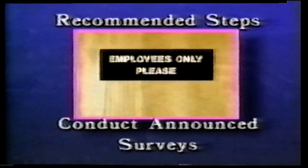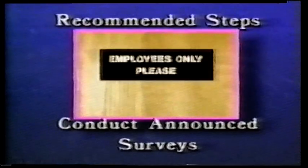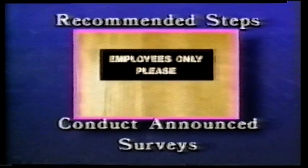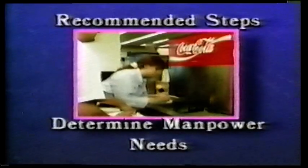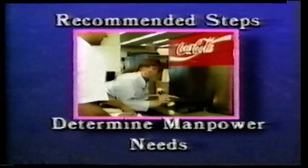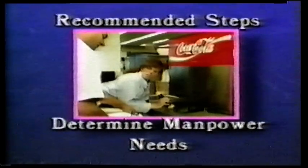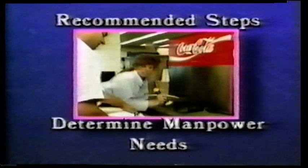Determine if the survey will be conducted announced or unannounced, and if appropriate, security clearances are necessary. It is strongly recommended to conduct announced surveys. Determine if the survey will be conducted by 1 or 2 survey specialists. Surveying in pairs, which is recommended, enhances the opportunity to detect cross-connections.